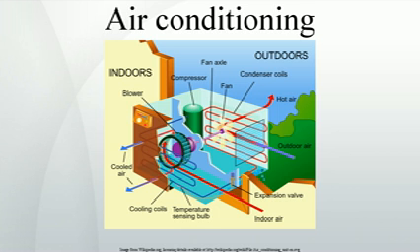is often described in terms of tons of refrigeration. A ton of refrigeration is approximately equal to the cooling power of 1 short ton, 2,000 pounds or 907 kilograms, of ice melting in a 24-hour period. The value is defined as 12,000 British thermal units per hour, or 3517 watts. Residential central air systems are usually from 1 to 5 tons, 3 to 20 kilowatts, in capacity. In an automobile, the AC system will use around 4 horsepower, 3 kilowatts, of the engine's power.